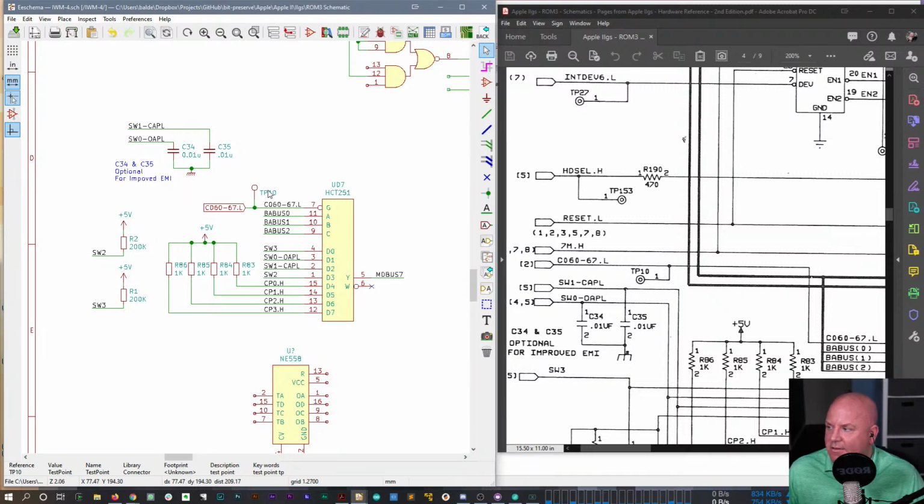Yeah, and I guess the one other caveat I should say there is if it's a multi-layer board where there are strip line traces running, then that becomes really difficult. At least with top and bottom layers, you can sort of see where the layers go. But if anything goes into one of the middle layers, yeah, that gets really tough. But again, if you know what the schematic is, you can sort of work out that this pin on the chip and this pin on the chip should have a connection somehow. And so you can at least work that out. But if you don't have the schematic, then that's going to be really tough.